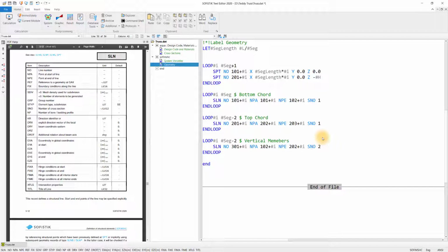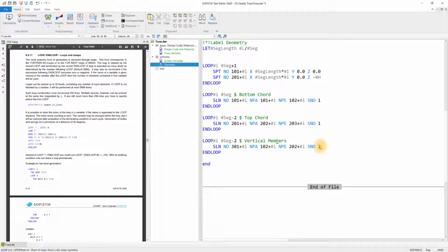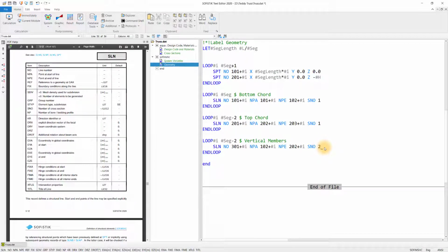We might also want to assign a hinge, and we will do that straight away. So the hinge for the beginning of this vertical member, I just see a typo, members, I use the command fix a. And, sorry, not fixation, actually it is a hinge, so I don't want to have any moments in my hinge.